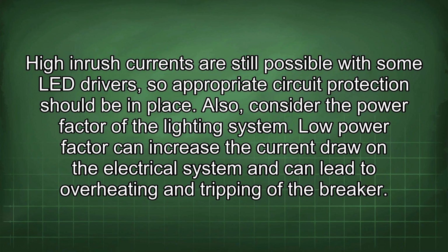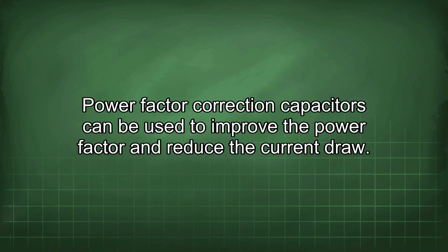Also, consider the power factor of the lighting system. Low power factor can increase the current draw on the electrical system and can lead to overheating and tripping of the breaker. Power factor correction capacitors can be used to improve the power factor and reduce the current draw.